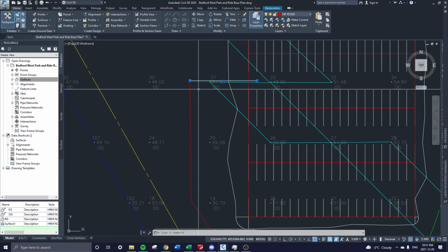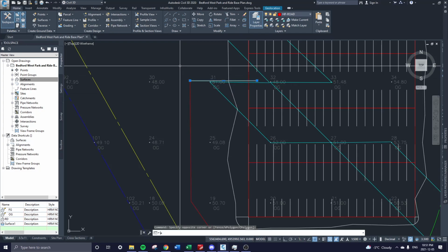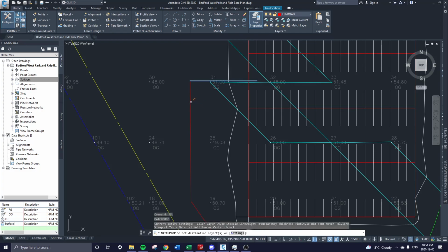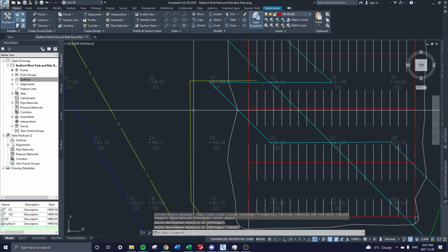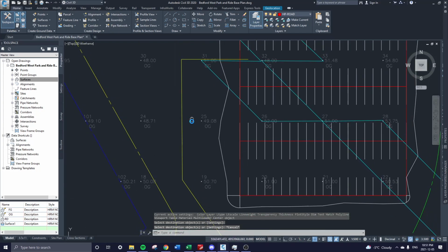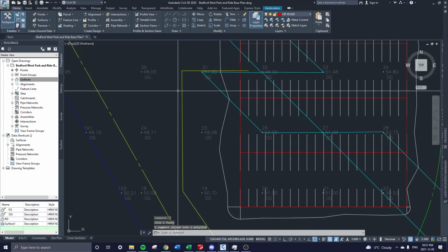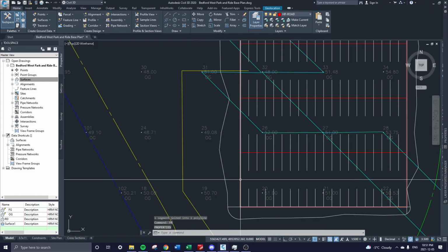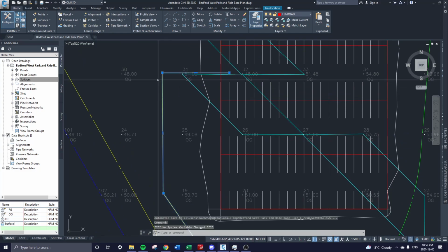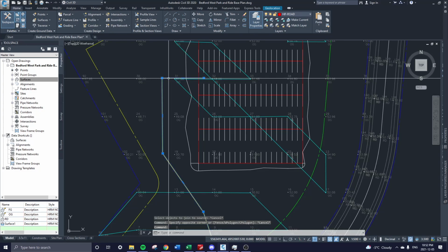You select the source of the line that you're drawing, type MA for match properties, and then you can pick whatever you want to be, it'll just look like the thing that you've selected. It's a nice little trick that can save you time instead of going into your properties and changing it all. It can be a little cumbersome. Okay, so I'm going to make sure this is all one solid line.